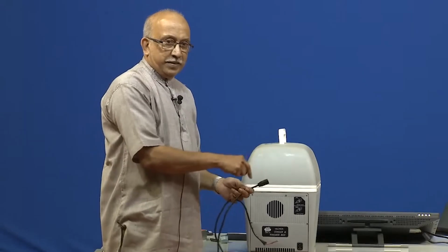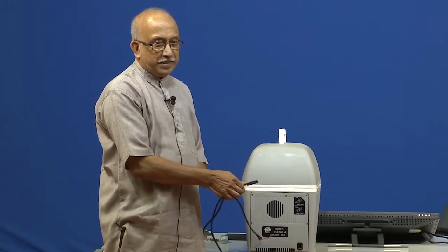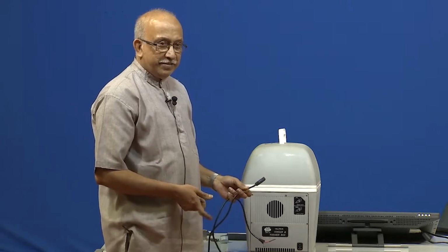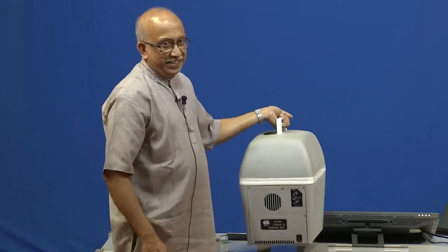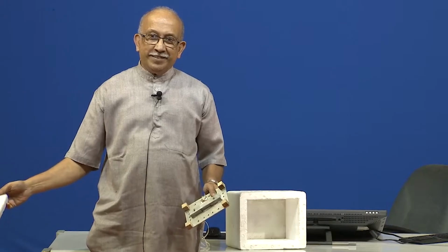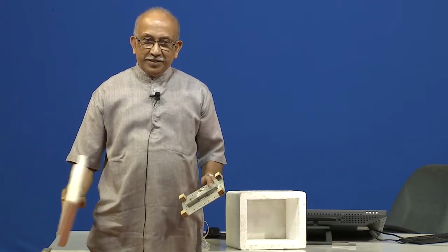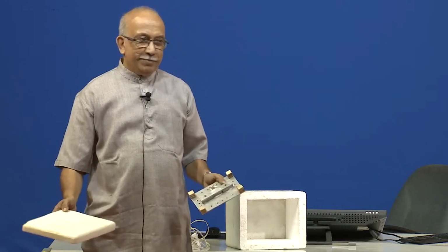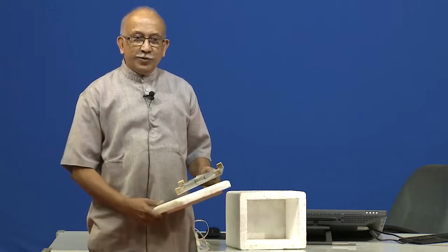If you connect plus to plus, it cools. If you connect minus to plus the other way, it warms up. For some reason, in either condition, it is giving smell and smoke. So that means we have learnt our lesson. For a warmer box, you do not need to have all that control, and Peltier is not very practical in a heating application. However, if you want to do both heating and cooling, there you want it.